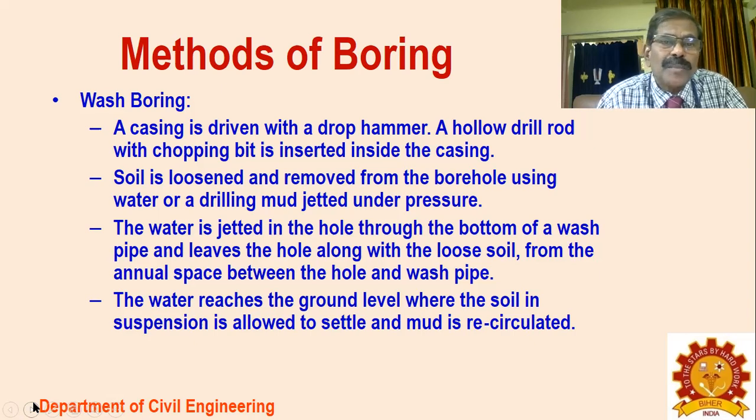That's how the method of boring works. In wash boring, you just insert a sleeve into that and then apply a pressure of air mixed with water, and the soil gets pumped out along with the moisture. Then it is collected, dried, and filtered very carefully, and the soil is recovered. Then it is tested in the laboratory.